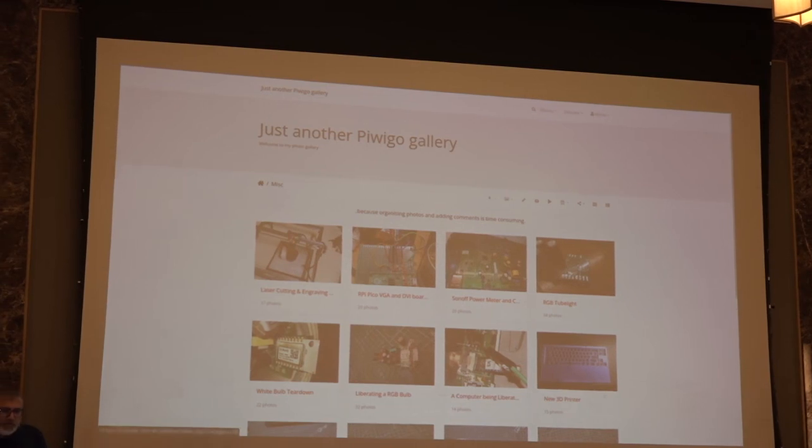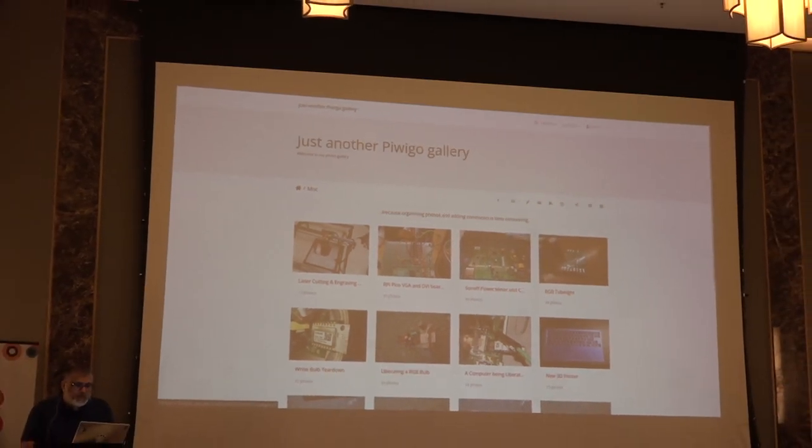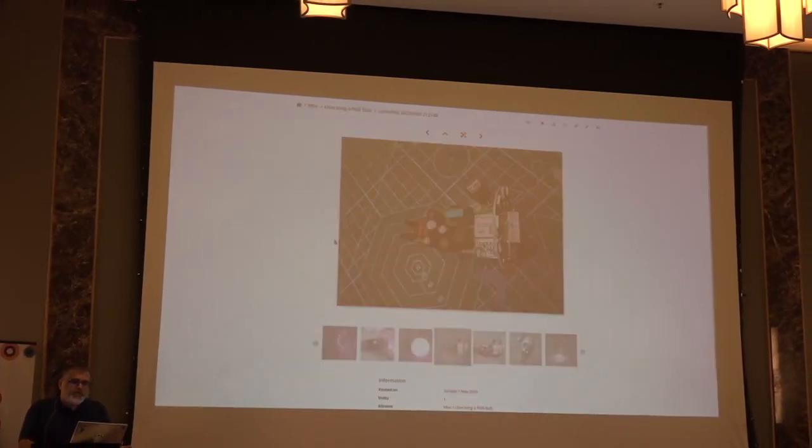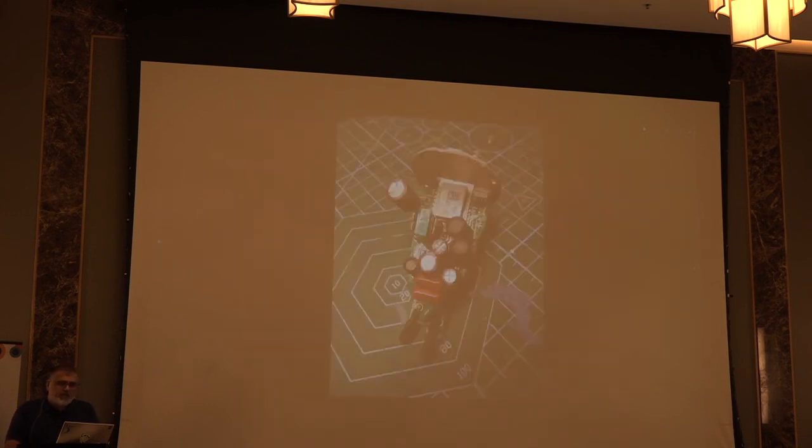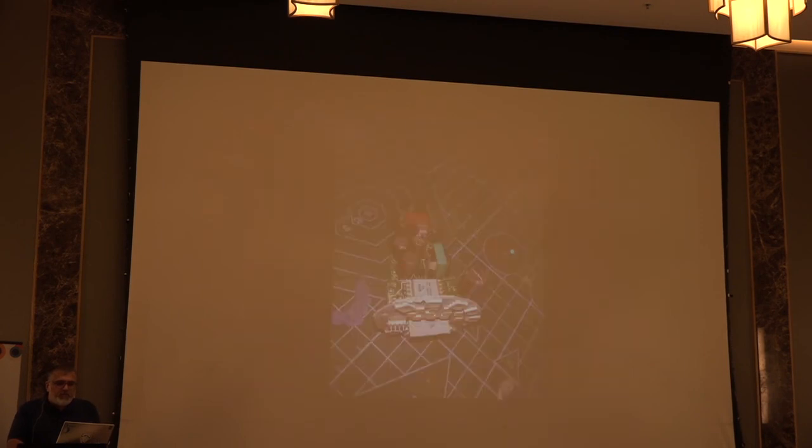Similarly, I could quickly show you bulbs. So this is a bulb. This is an RGB bulb. So this is the controller for it. There's a lot of power circuitry here. And then there is a microcontroller here, which is the Wi-Fi microcontroller. So what happens is, this board here on the top, the round board, has multiple types of LEDs. It has very powerful white LEDs, which give you plain white light, and then it has the RGB LEDs for changing the color. And then you can mix these to change the brightness of the bulb.